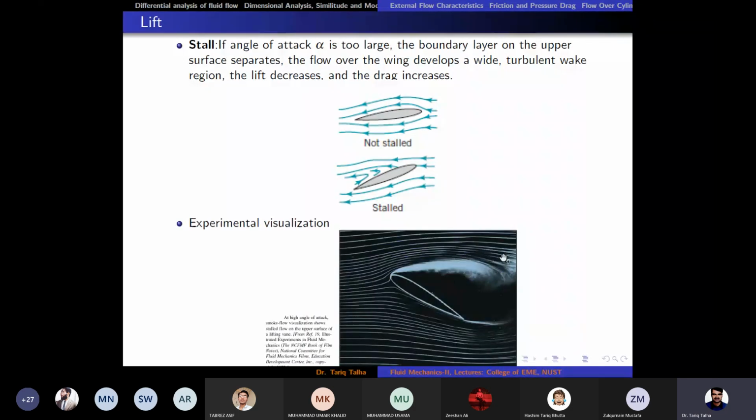That is the flow separation region where we can see huge flow separation. The lift force would be higher, but because the drag is very high, the velocity and Reynolds number would decrease and lift force eventually would decrease, and the aeroplane is doomed to crash. That is not a very ideal thing to have.